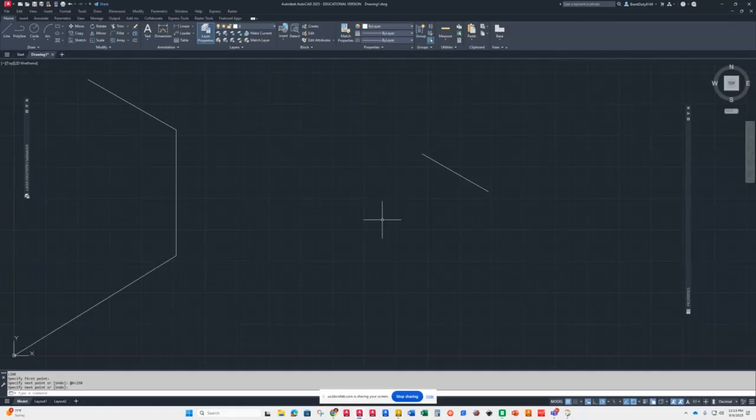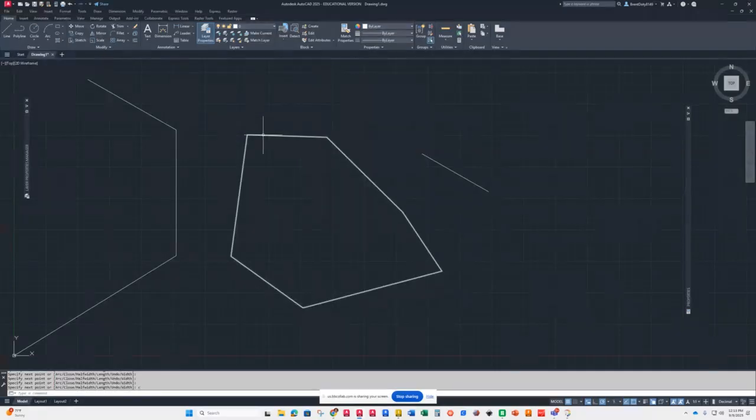Like that. Now, that's a polar angle. So that's how you can use the line command. Polylines are basically lines that are connected, and if I hit C for close, then it makes it a better polygon, if you will. A polyline is all connected. The line command makes separate lines. So this is how you would do something that you want all connected.